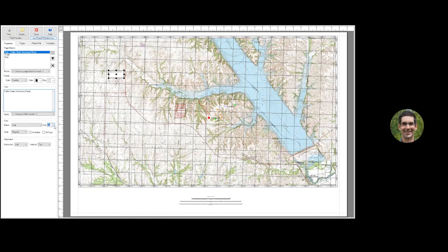It's very small right now, so we'll change the size to a much larger font size. Let's do 36, and you can change the font type here if you would like. We'll move it down here, change the style to no frame, and bring it out large enough so it actually fits on the screen. Okay, that looks good for my title.